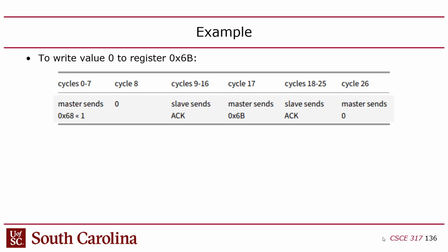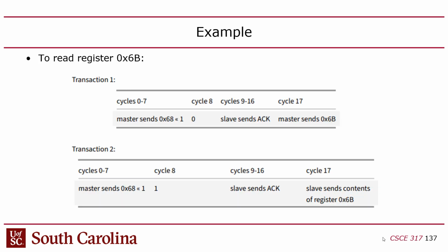And it sets it to the plus minus 2G sensitivity, right? I think it's in that register, right? Yeah, so this turns it on. This is how you turn it on. You write to this 6B, right? But then once it's on, you're pretty much going to just be reading from it, right? Because it's a sensor, right? Sensors, you want to read from sensors, right? So to read, I'll fix that, by the way. Sorry about the formatting error there.